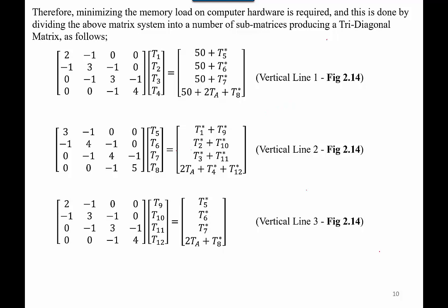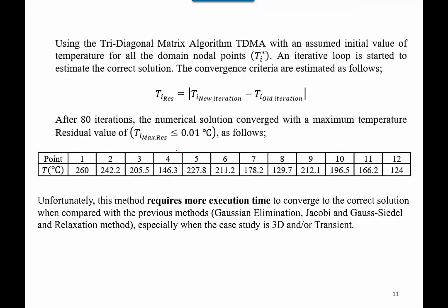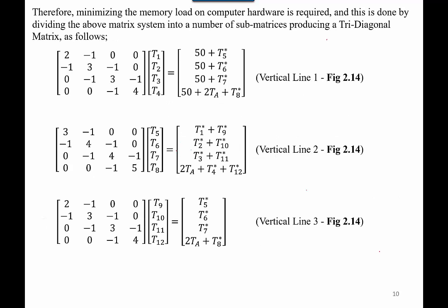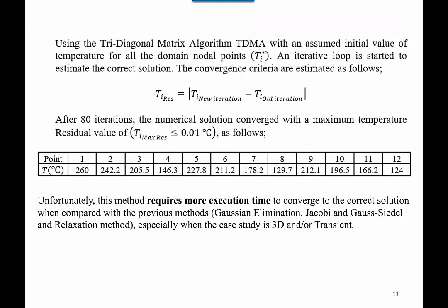So therefore, as we see here, all these three submatrices are a tridiagonal matrix. So therefore, we can solve it by computer using the TDMA method. And it may be 3 submatrices or 15 submatrices. It depends on the cut of your grid, how many vertical lines, or maybe you follow the horizontal lines. So therefore, you will use the TDMA method in order to